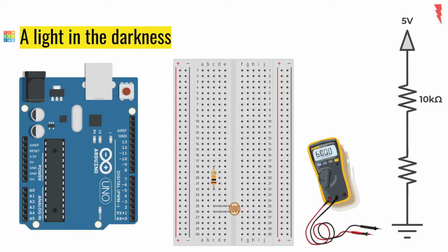Now, let's say that we add a second resistive element to the circuit in series with the first. So, 5 volts goes to resistor 1, through resistor 2, and down to ground. If you were to have two of the same value resistor, in our case, two 10,000 ohm resistive elements, then you know that the top value is 5 and the bottom value is 0. What would you guess the voltage reads at the middle, the point where the two resistors connect? It should read 2.5 volts.